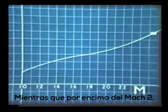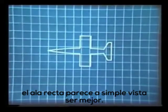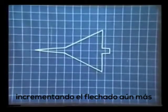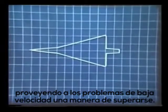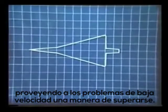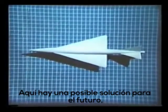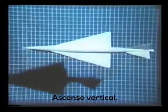While above Mach 2, the straight wing planform seems at first sight to be better. But drag can be reduced still further above Mach 2 by increasing sweep still more, provided the low-speed problems can somehow be overcome. Here's one possible solution for the future. Vertical takeoff. Shapes like these may well be the supersonic airliners of the future.